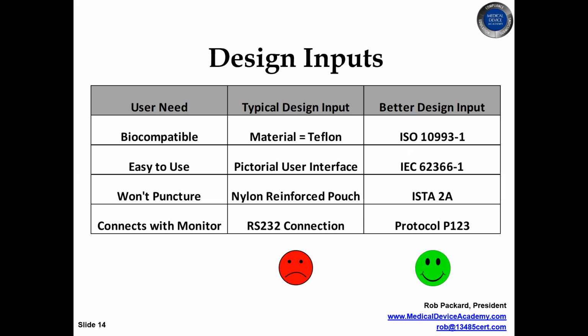That's not a verification test. A verification test for this type of input would be, or I'll list the input, it would be, I want you to put a multimeter on this point and this point and measure what the resistance is across the circuit. And based on that, it has to fall within these criteria.